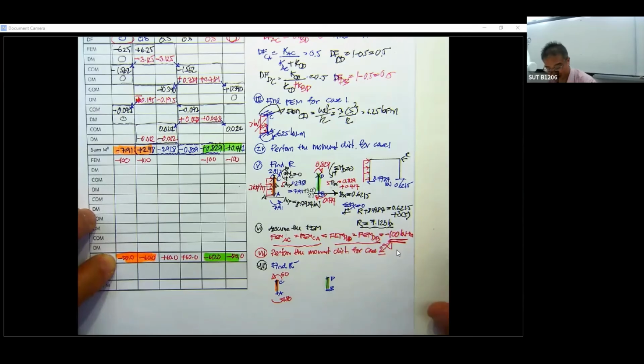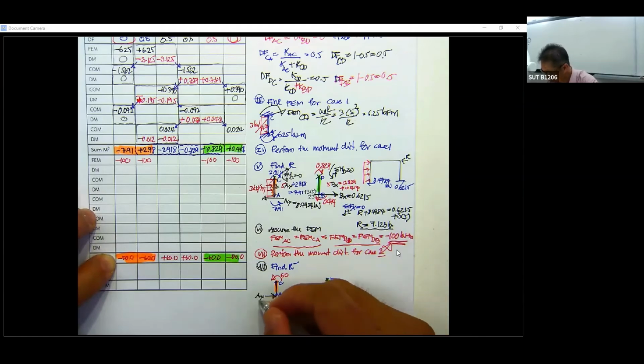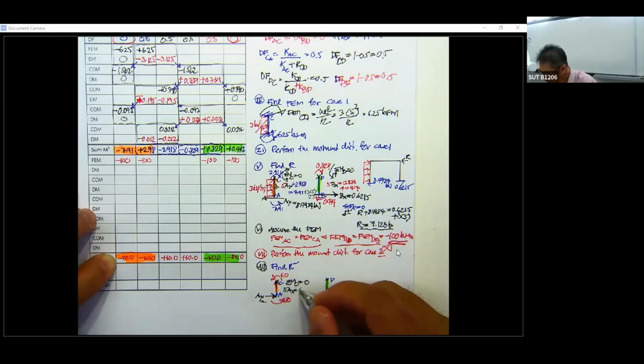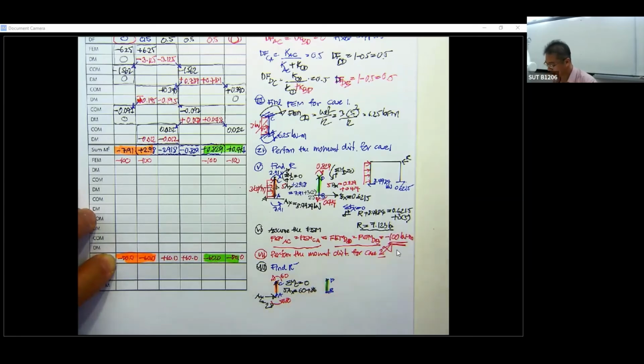That is 60 negative. Okay, and since all of them rotate like this, I'm very sure the force that occurs is negative, right? Yeah, it's negative. It's going to be the force A sub x over here. If you take the summation of moments at C equal to 0, you will get A sub x times 5 equal to 60 plus 80. So your A sub x is going to be 140 divided by 5, which is 28.